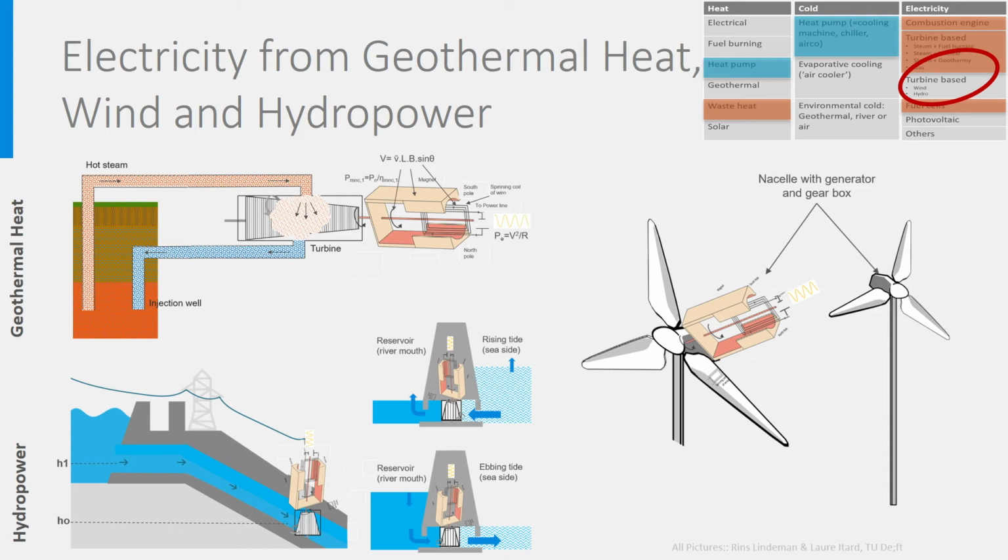In practice, approximately 27% of the energy contained in wind can be transmitted to the rotor. As the efficiency of the generator in these turbines is around 0.85, this brings us to an average electrical efficiency of around 23%. But that's not really a problem, as wind is fully renewable, its primary energy use is zero, as are its CO2 equivalent emissions. There are a lot of losses in such a wind turbine, but they cannot be recovered. Gone with the wind. So, combined heat and power is not possible.